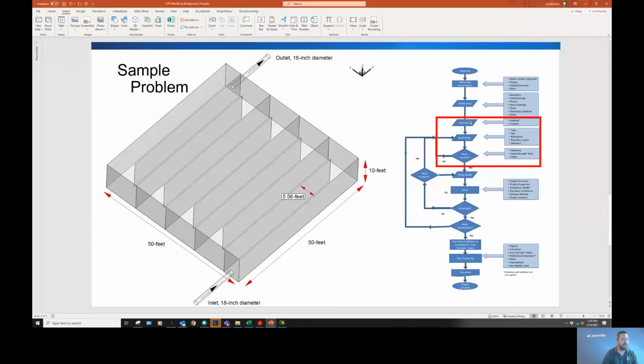And so here we've gone through the geometry creation, building the mesh. We've done the quality checks. The mesh is good, so we're ready to go set up the model in the solver. We'll take our initial run through. Everything's converged. We would continue with the mesh independence study, and then we'll update this mesh to make sure we have sufficient resolution to solve the problem before we proceed into the actual flow conditions of interest.